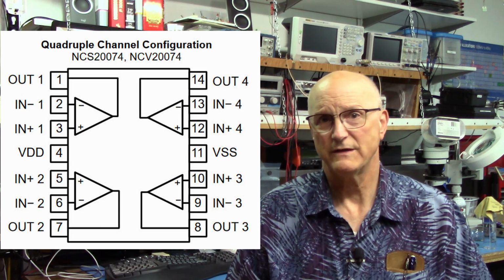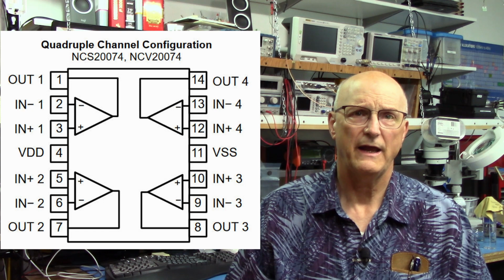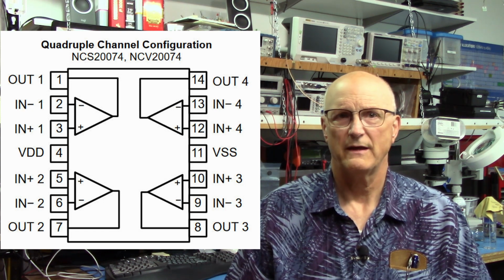I will follow this exact scenario with channels 2 and 3 and the output amplifiers. I will do a quick arrangement of the parts just to get them in their respective places all lined up. And then we get to place passive components around the channel 1 input amplifier.